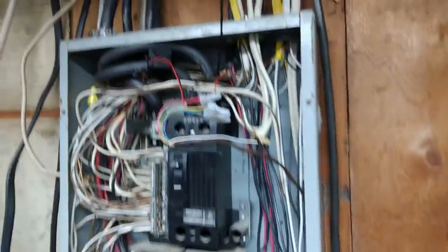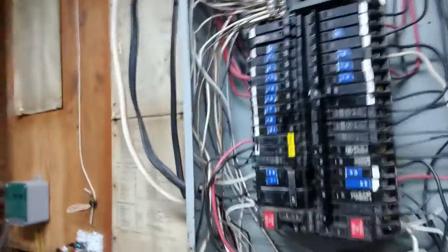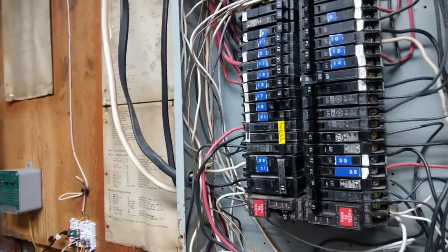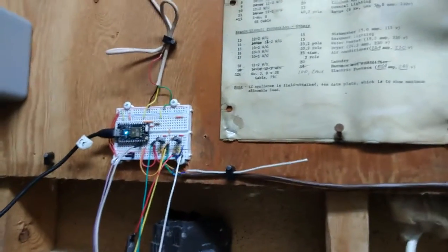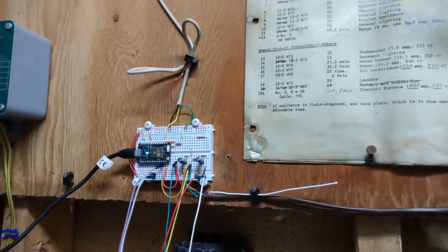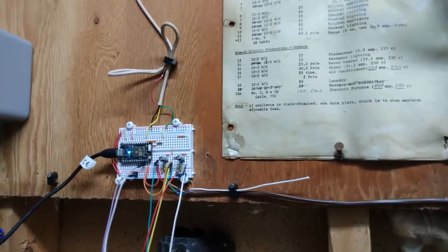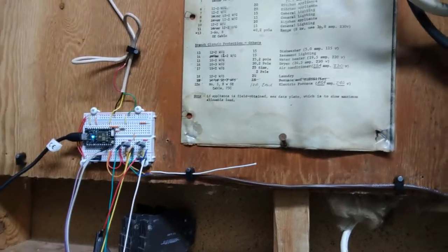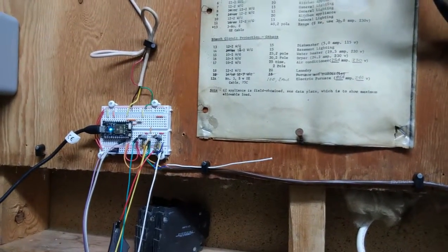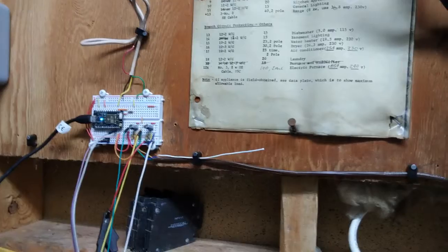So we essentially have the CTs connected in the top of the breaker panel, comes down, measures all the current that's fed into these branch circuits, and then it comes over here into the Photon. We got a positive bias voltage divider so that the Photon can read it, and sends it over to Keith's stuff, the Google Sheets, and Keith's got it crawling through our spreadsheets every night, and he's going to show you how to do that. So Keith, I'll turn it over to you.